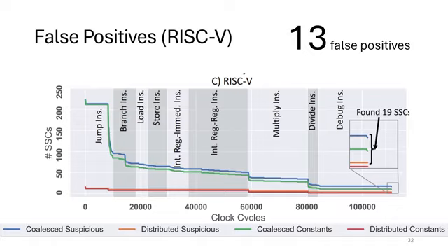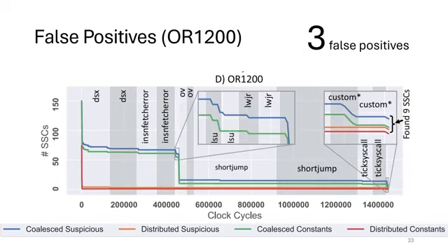and not something more complicated designed to utilize all the registers fully, which makes this OR 1200 test also very odd because they do repeat instructions in this one. They do each instruction twice. They use 7 default sets of instructions, and they use one that they designed themselves. It's custom to test the configuration registers. So they added a custom instruction to test those specific registers.